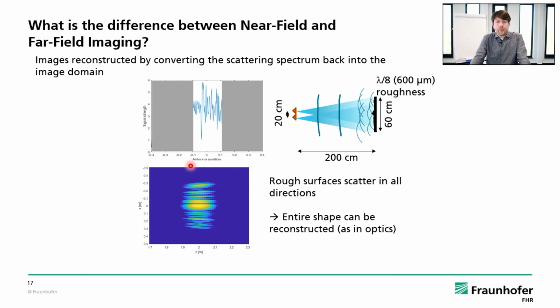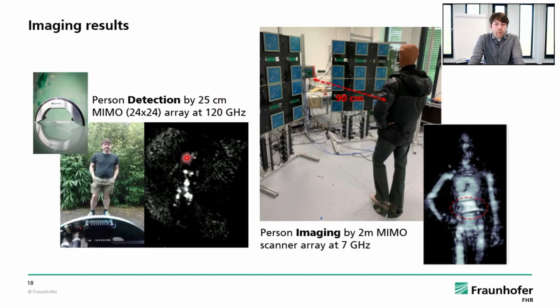Like making a video of a mirror, you see the background, but you don't see the mirror itself. And if you look at the results we get from smaller and from larger modules, you see that. We are developing very small integrated radar modules. Here, for example, some of you might have heard of the Smokebird project, where we developed MIMO radars at 120 gigahertz with 24 receivers and 24 transmitters, all integrated at 25 centimeters.